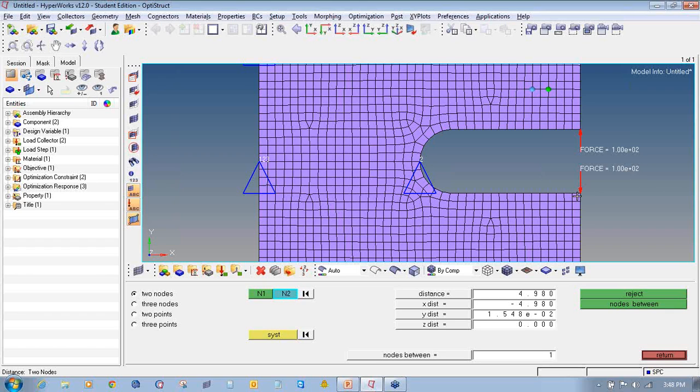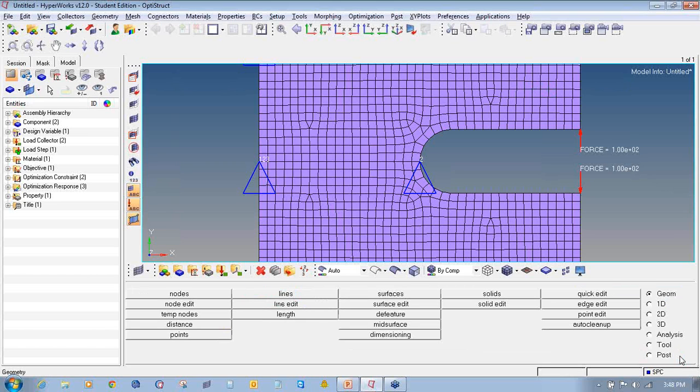So it is recommended that the minimum dimension value be 3 times larger than the average element size unless the element mesh is aligned, in which case it can be 2 times larger. So the general rule for minimum member size is that it should be 3 times the size of the average element size. So whatever the average element is, it has to be 3 times.